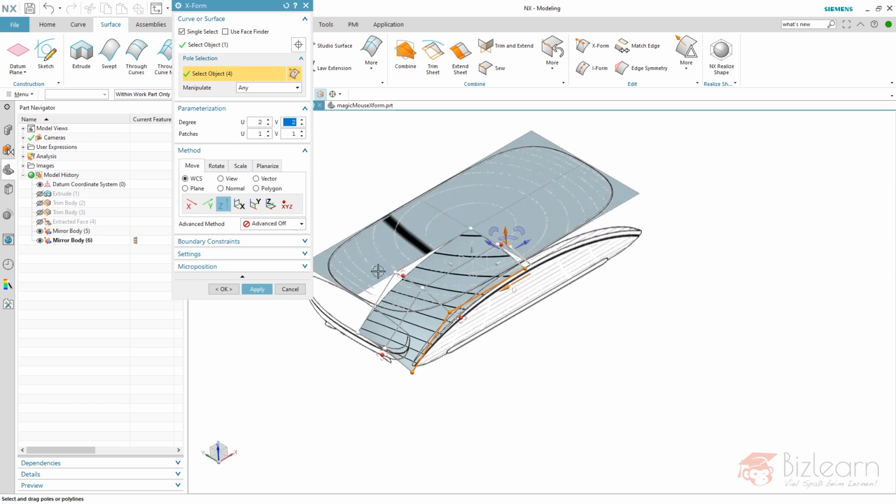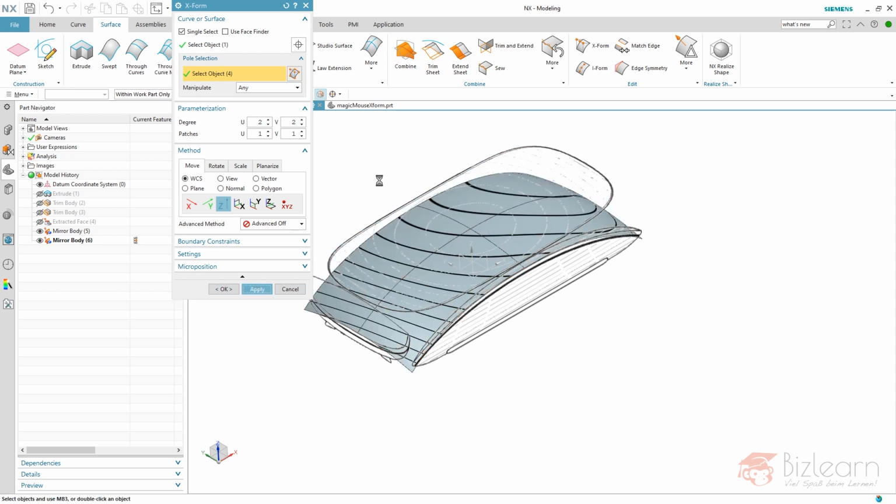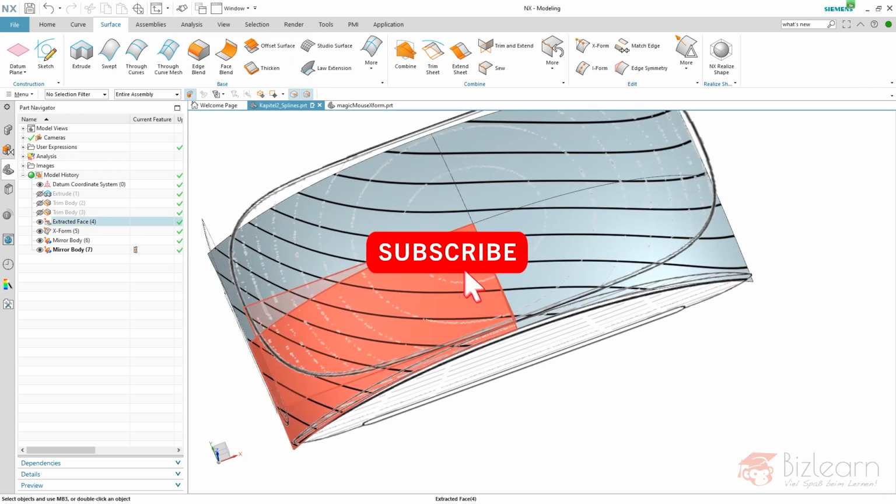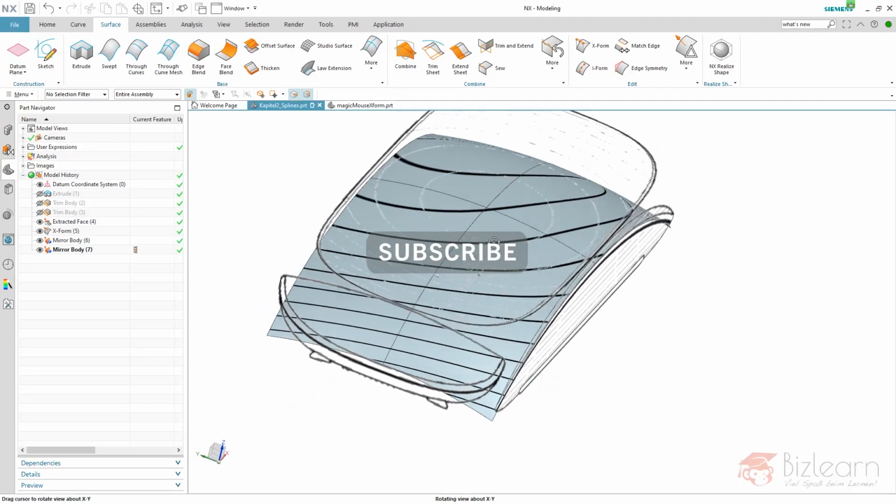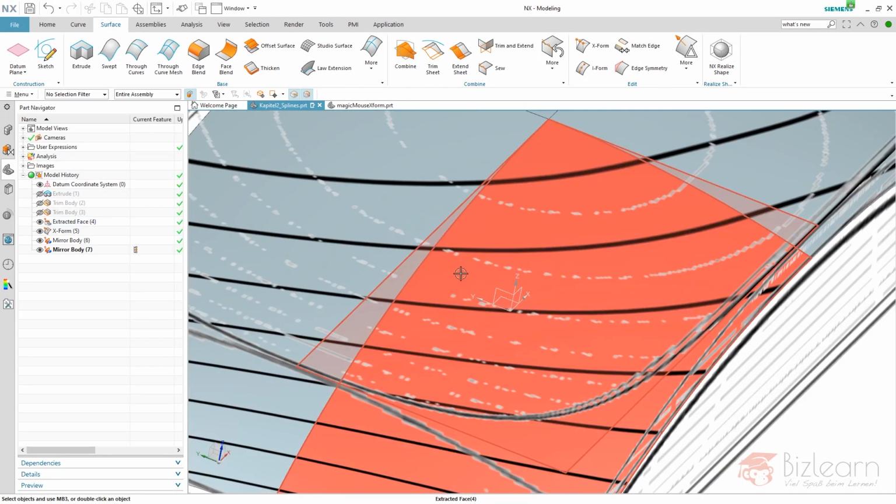And of course, there is no update right now of my copy, so I'm just gonna apply this. And we're still tangent and we're still curvature consistent. If we had an angle between the lines, it would tell us that we're still tangent but not curvature consistent. Curvature consistency, what does it mean?